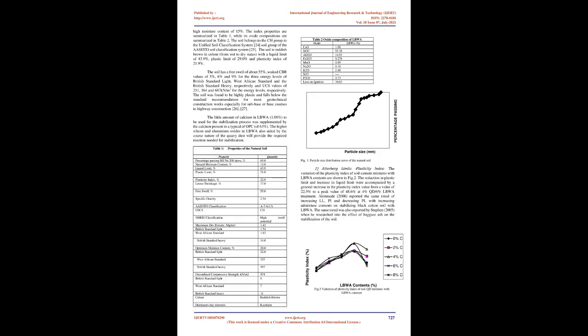Quarry dust. The quarry dust used for the work was obtained from Bora Garden along Offa Ajase Road close to Green Park, Ajase-Ipo, Kwara State. The materials were kept properly in a closed container and air-dried before passing through sieve no 4.75 mm. Locust bean waste ash. The locust bean waste ash, LBWA, used was obtained locally from burning the husks sourced from Igbara village along Offa Ajase Road, Offa, Kwara State.